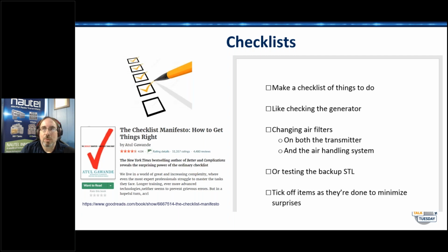So by all means, put those sort of things, even if they still test good. I mean, controller batteries, ours typically will throw you an alarm, and they'll last 3 or 4 years at least, depending again how long the transmitter's on or off. But the thing to remember here is if you come into snow season in September, October, and can't get back to the site until May, you'd better have replaced that battery in August or September. Otherwise, November 1st, you're going to get the alert that says, hey, this battery's about to die. And then you're at the mercy of power outages and how much grace was built into the battery monitoring system. So absolutely, the need is there for that.